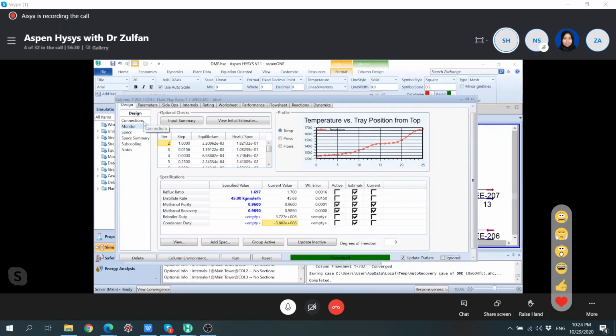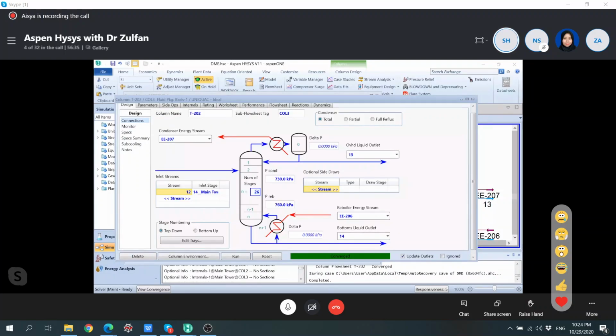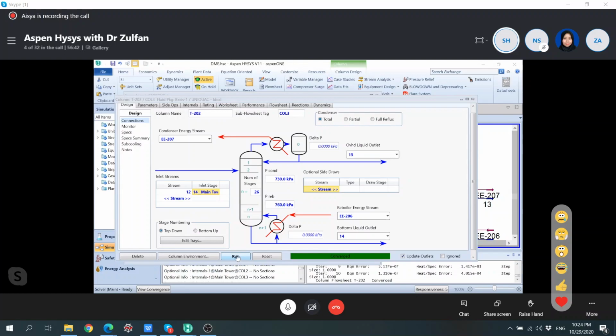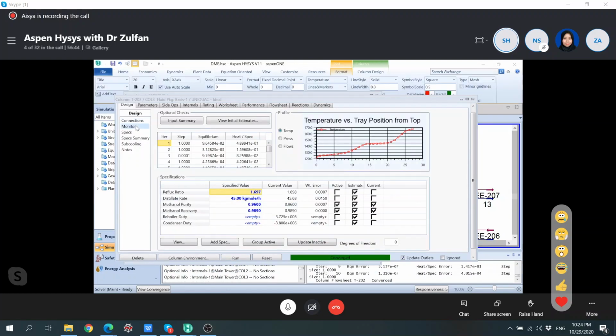We can use that as the capex, also for the reboilers if you want to. The other option is Aspen, which has the Aspen Economic Analyzer, so you can run it and have the comparison as a function of the number of stages. For each of these stages, we get the capex and the opex. The opex is a cost in time, but the capex cost has no time.